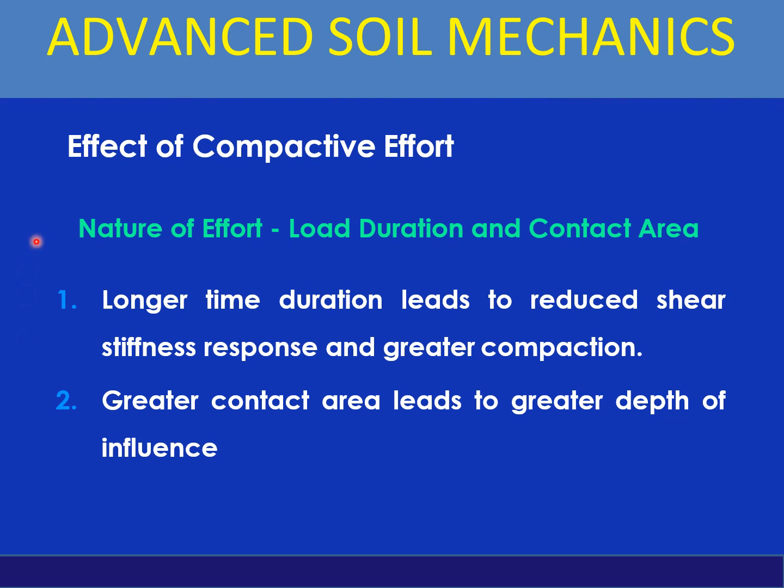Nature of effort: duration and contact area. Longer time duration leads to reduced shear stiffness response and greater compaction. Greater contact area leads to greater depth of influence.